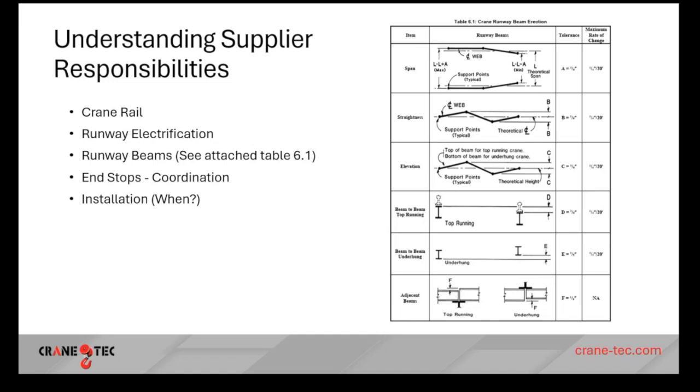Because they're on 2 separate frame lines, each crane. And this particular building has parallel cranes, 2 separate over 100 foot long parallel cranes. And if the building's allowed to be out 1 13/16, you would expect that they would slot the holes. So the subs that are working on straightening that crane rail are, I think rightfully, a little bit concerned that that adjustment was not built into the manufacturer's supply of the crane rails.